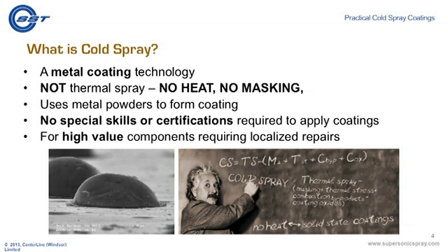Now, before we get into the formal definition of cold spray, I want you to imagine something for a second here. Imagine a control unit about the size of a 2-drawer filing cabinet with wheels on it. So it's portable, you can move it around. Also imagine something about the size of a handheld hairdryer, with a 1/4-inch exit nozzle. Now connecting these two is a 1-inch diameter flexible conduit. Imagine coming out of the end of that 1/4-inch nozzle metal particles traveling between 300 and 700 meters per second directed towards a target. The target is either a metal or glass. You're going to make a coating on that substrate. That's basically what cold spray is.